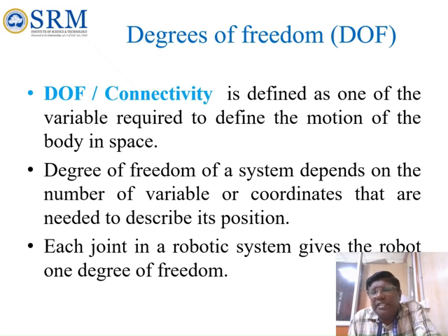If it is a turning pair, it can give 1 degree. If it is a spherical pair, it can give 3 degrees of freedom also. So say X, Y, Z, where it can move. Okay. Suppose if you are having a turning pair with 1 degree of freedom, it can move in the X direction only, which means the degrees of freedom is 1. So if it can move in X, Y, and Z, it has 3 degrees of freedom. Okay. So in simple words, it is a movement.